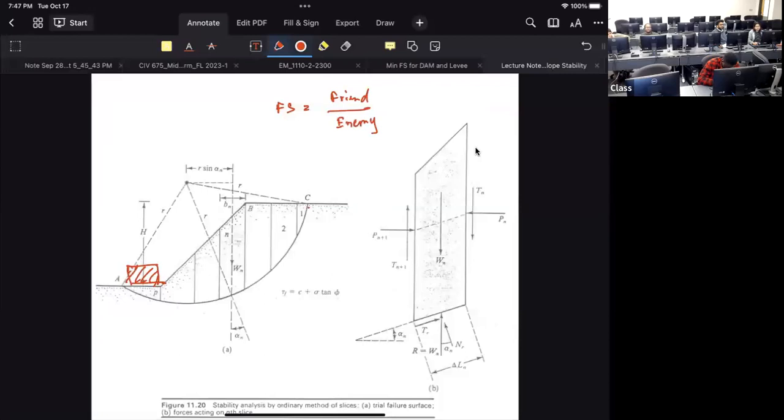So if we see the slope is failing, what is the best immediate action you should do? You can put some load, a bag of soil, at the bottom corner, at the toe. Launching apron type things, launching apron.